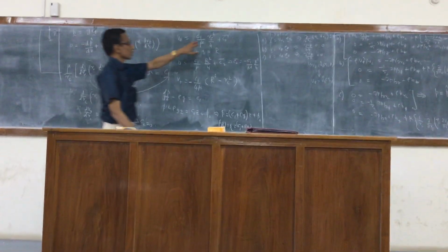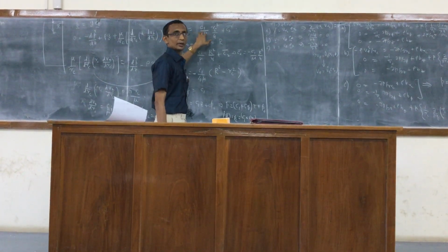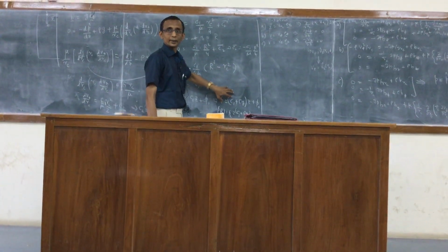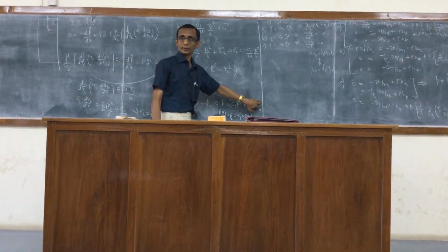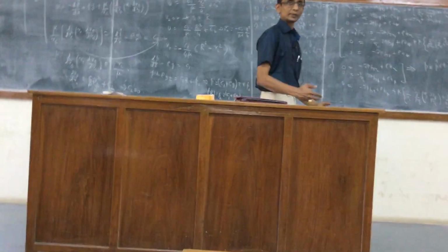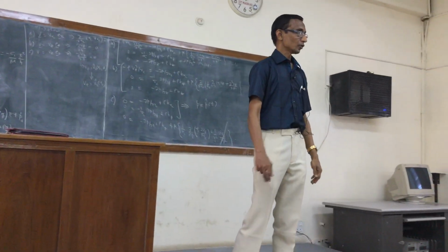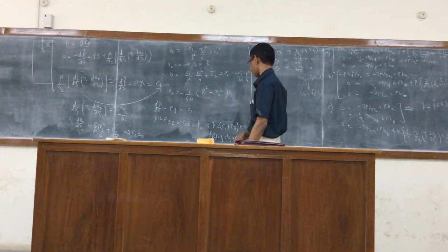And so one of the constants we determine using the no-slip boundary condition. So C1 is one constant that is not known yet. And when I try to get it from the pressure equation, I get another integration constant. Obviously, because it's a first order differential equation, the pressure. So now we have to deal with effectively 2 constants, right?